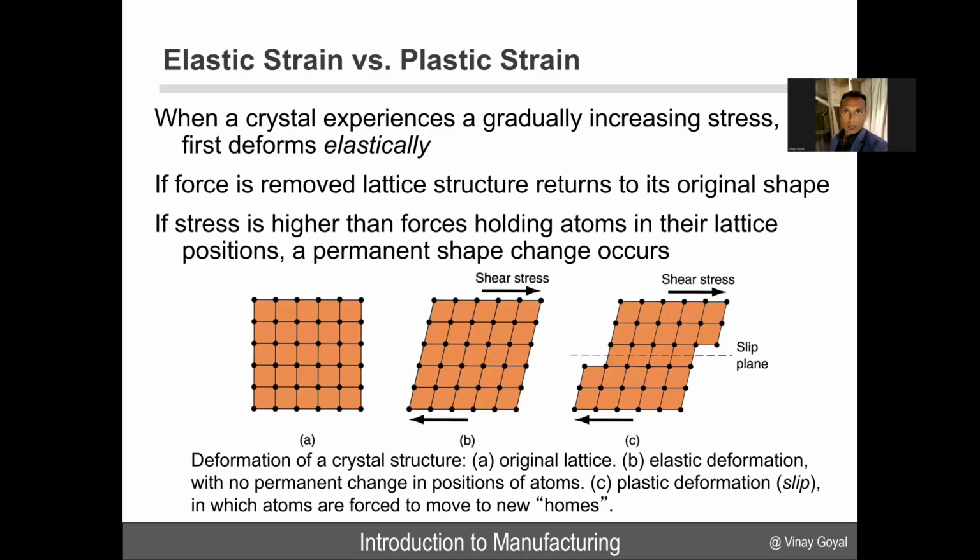So continuing on, we will compare elastic strain versus plastic strain. Recall elastic strain is a situation where if I load up a material, that material will deform, and then when I remove the load, it'll return fully to the original deformation or initial shape. In this case, all the straining that was occurring was elastic because all the deformation was recovered back to normal. With plastic strain, you do have some amount of residual strain that occurs, and that needs to be considered as